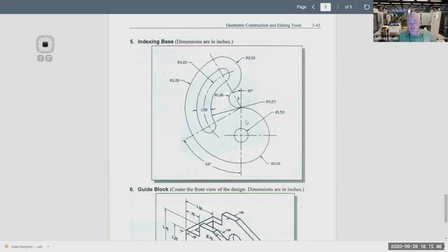So if you would be doing a technical drawing class and you would do a radius, it would always go to the circle. And so what's important to realize is that this circle right here on the left-hand side is not at this center mark. It's actually at this intersection right here. And if you know that, it's a lot easier.